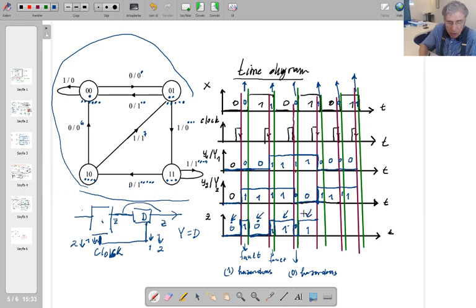So before the clock pulse, I am observing the right output, isn't it? For the first clock pulse, this one is not transferred to here. When the clock pulse comes, the Z value before the clock pulse is transferred to the output.